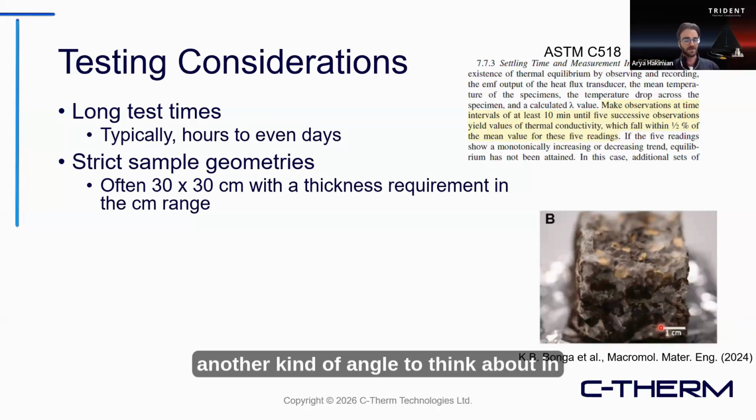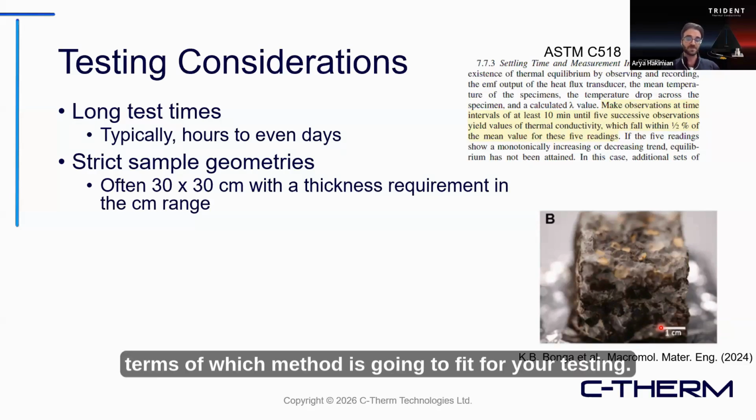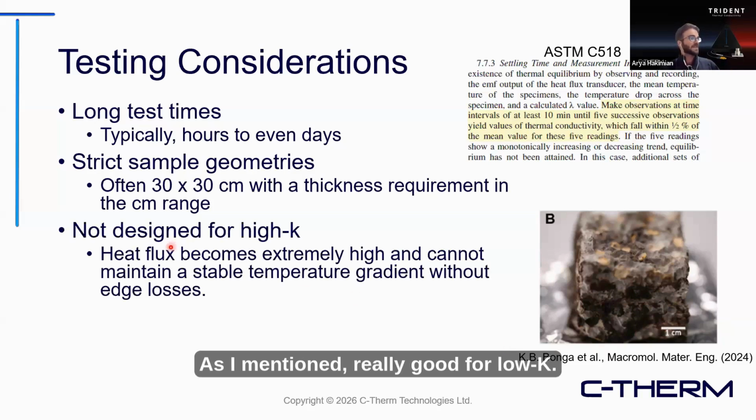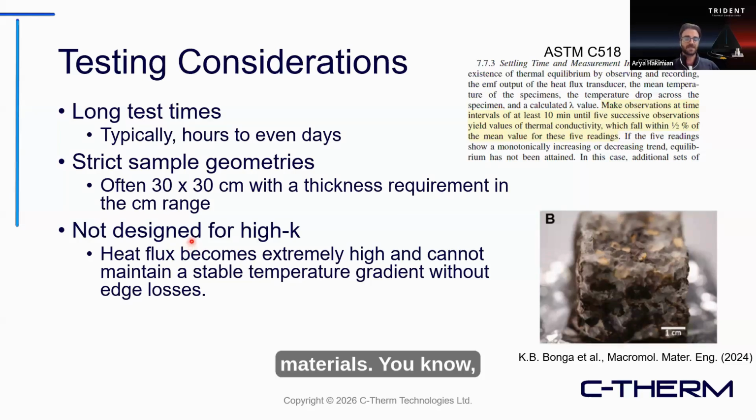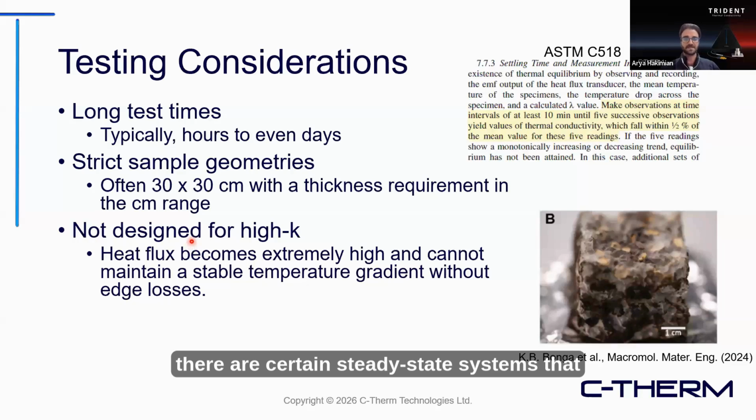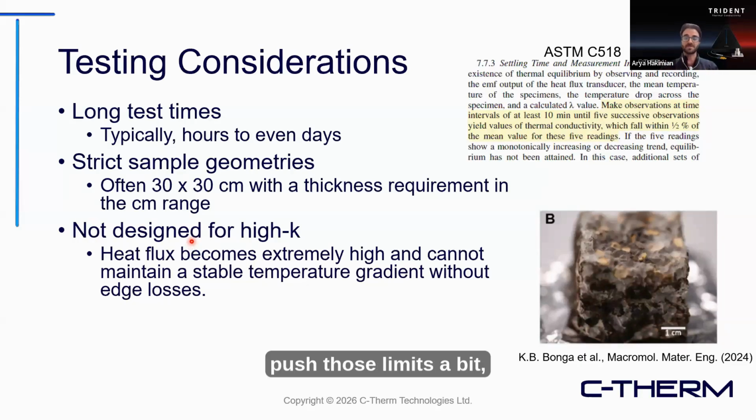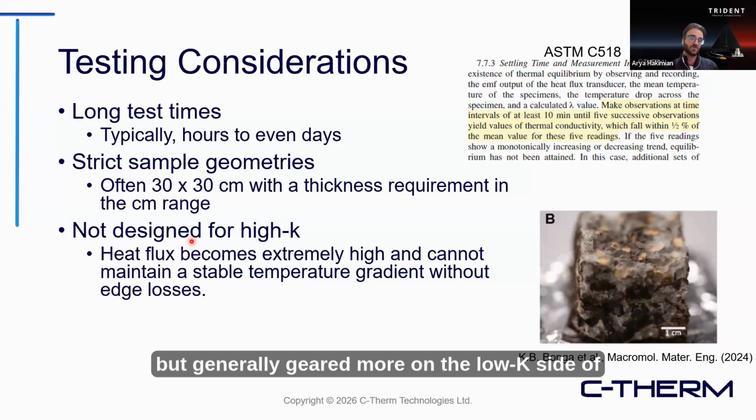So that's another angle to think about in terms of which method is going to fit your testing. As I mentioned, it's really good for low K. I'd say it's the industry standard for a lot of insulation activities, but not so great with the higher conductivity materials. There are certain steady state systems that push those limits a bit, but generally it's geared more toward the low K side of things.